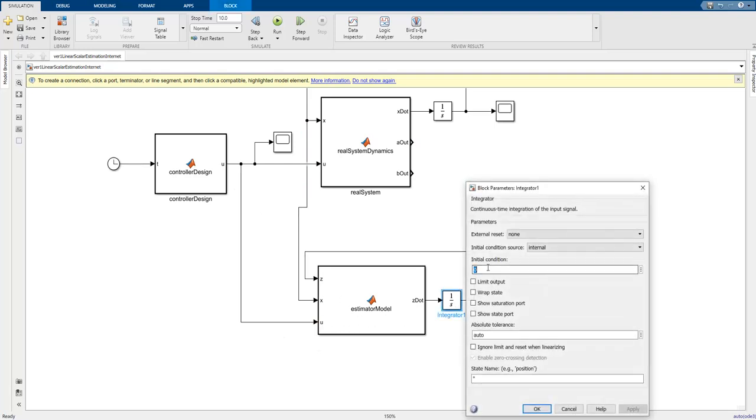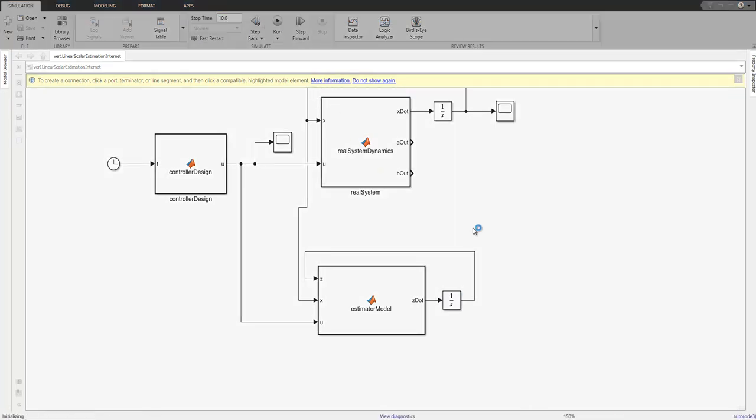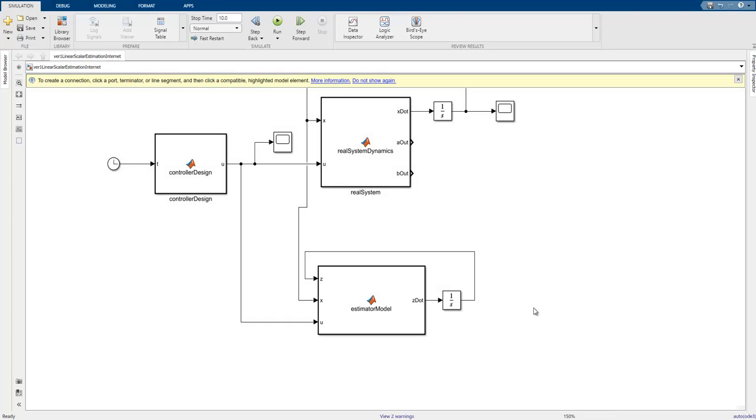And so this integrator should be in the form of a 3 times 1 vector, so I should choose 0 0 0. This is wrong, but why it is wrong I will explain. Okay, and so if I run this code, there is no syntax error in here, but we need to use the demux operation in here like this one,